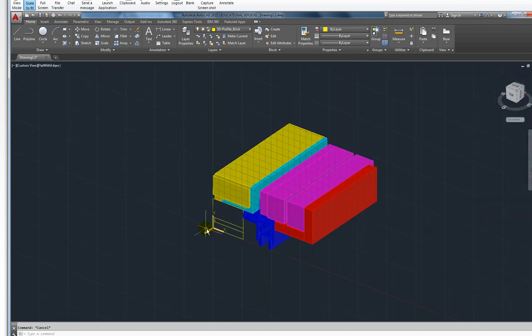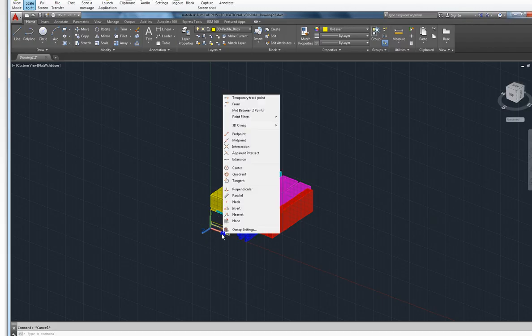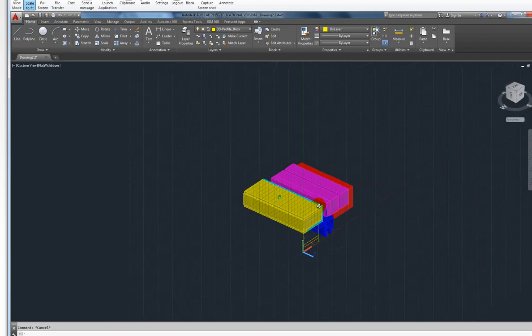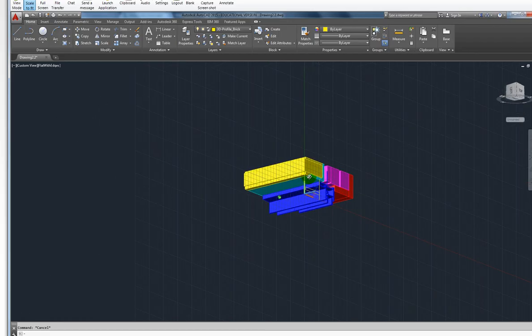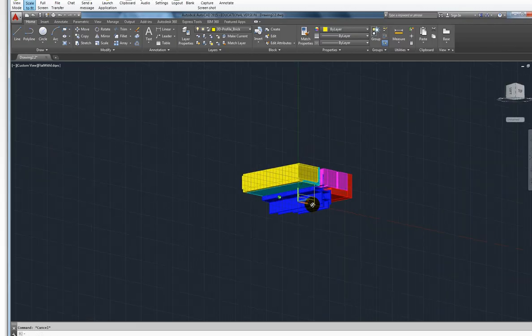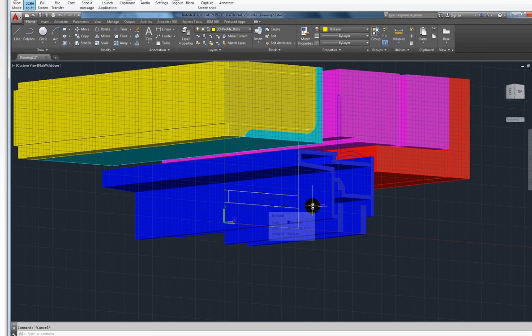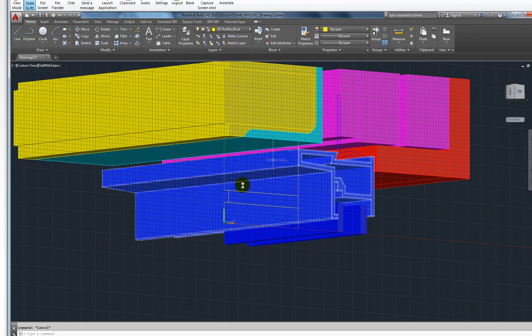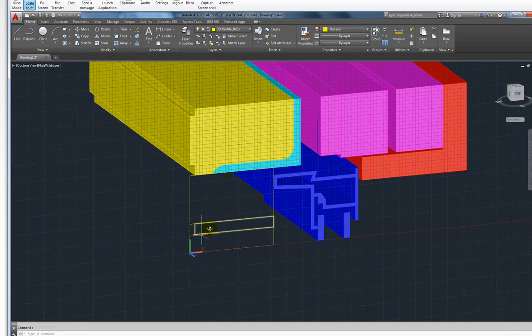Okay, so if I use my shift rotate, I can rotate. So this brick here and that mortar and that brick are back here somewhere. The back here is going to be the halfway point. So I'm going to extrude this the half amount. If I did 2 feet, I'm going to extrude this 1 foot. Does that make sense?